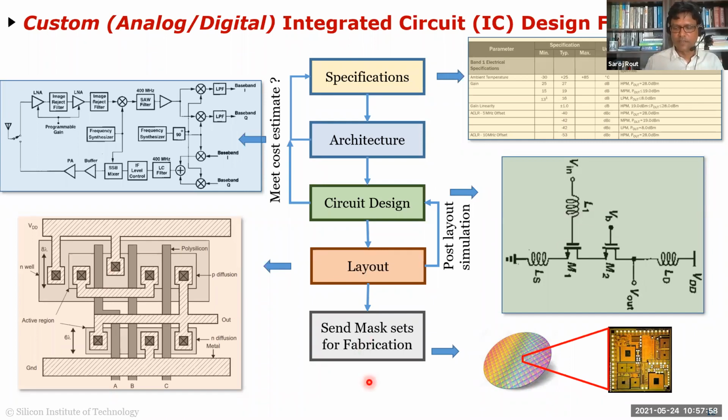You send it to fabrication, and those guys will take one wafer, like a 6-inch or 8-inch or a 12-inch, the circular thing called a wafer, and fabricate thousands of chips or 100 chips, like an Intel Itanium processor. They'll probably only be able to do 10 or 12 because those chips are huge. Whereas like the accelerometers I was showing you, some of them are 0.3 millimeters square. So you can fabricate about 100,000 to 500,000 devices in one wafer. Okay, and they will cut and dice it and send you those tiny squares.